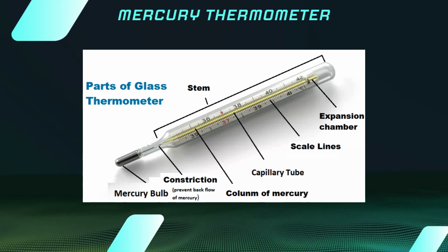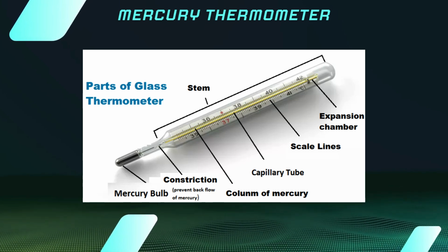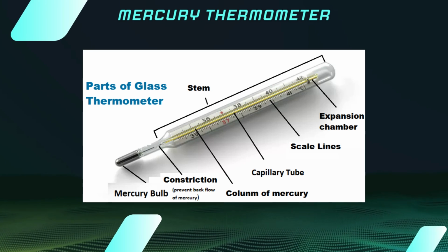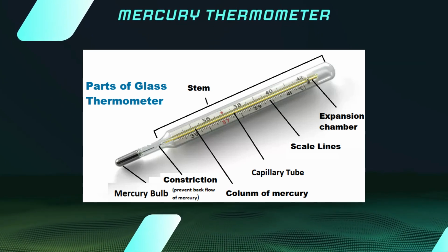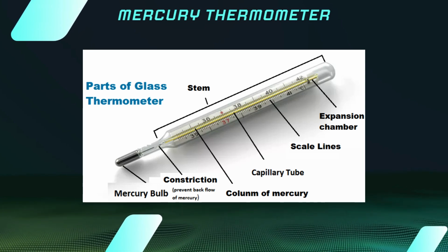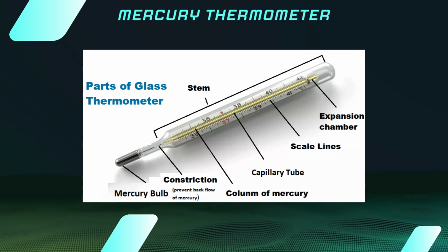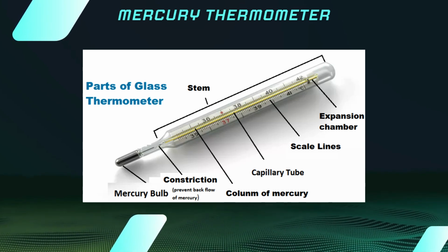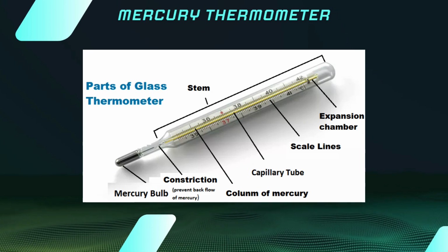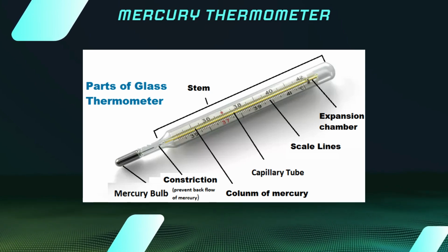The first general instrument in question that I will introduce is the thermometer. One of the most basic installations and first image that comes to mind when you think of a thermometer is the mercury thermometer, the type that you find in the laboratory. It consists of a capillary tube joined with a bulb containing mercury at one end of the thermometer. The capillary tube along with the bulb are encased in glass that is lined with a reading scale measuring temperature in unit degrees Celsius.